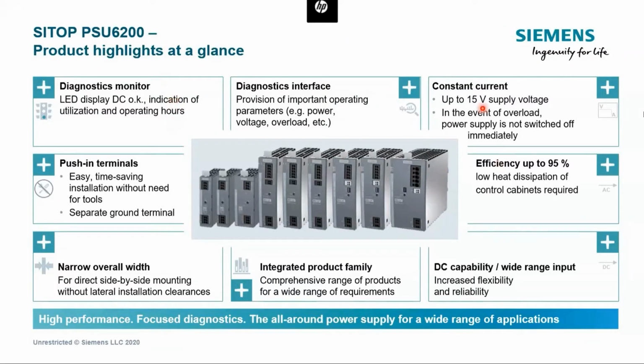Another interesting feature is the diagnostic interface. You remember we said that we have a signaling contact in the power supplies, which indicates to a PLC that the power supply output is okay or not. Now, for this power supply, we have further improved this. We connect this signaling contact into a digital input of a PLC, but it is not just a digital input.